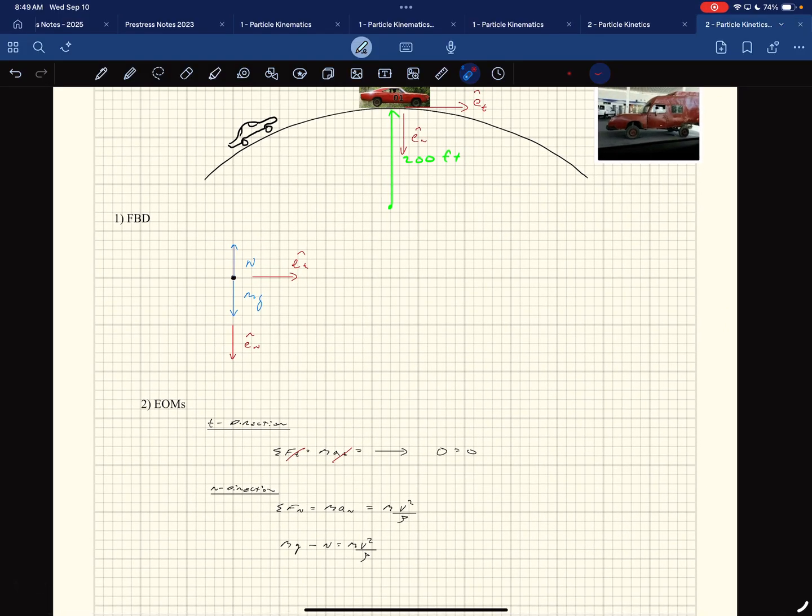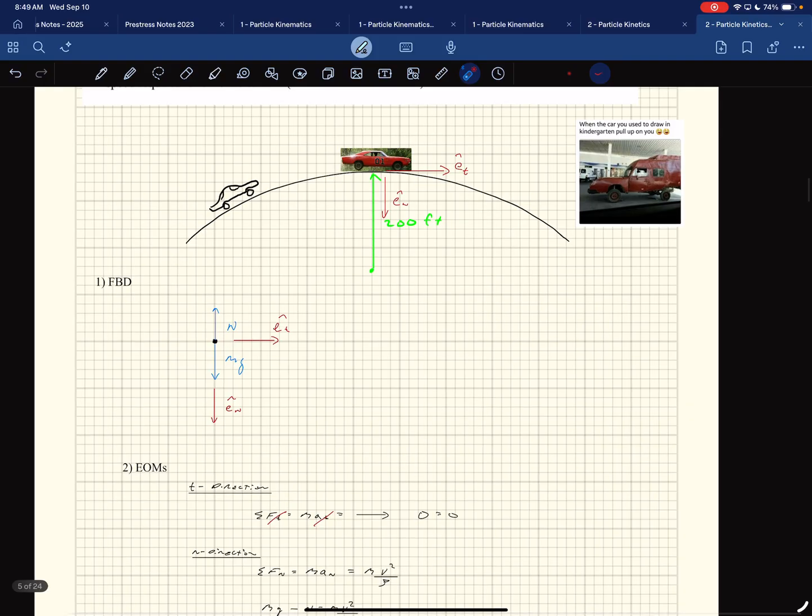When it's jumping, that's the bifurcation point. When it's equal to 0, it means it's just going to start lifting off, because we're trying to find the minimum speed required so it lifts off. And so in that case, that normal force will be equal to 0, right at that point. Can that normal force be acting down and end up being a negative value?